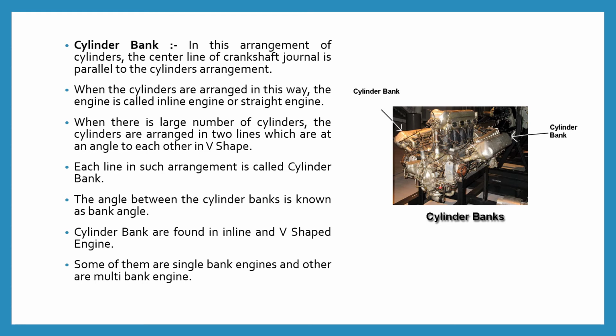So students, basically in the cylinder bank arrangement, the center line of the crankshaft journal is parallel to the cylinder arrangement. When the cylinders are arranged in this way, that means in the cylinder bank position, the engine is called an inline engine or straight engine.